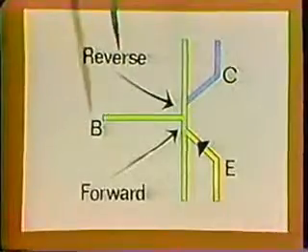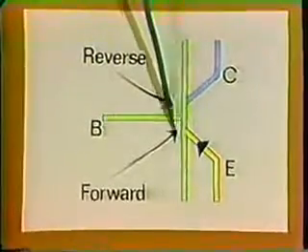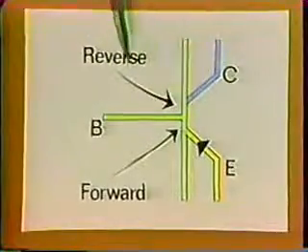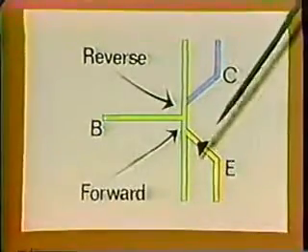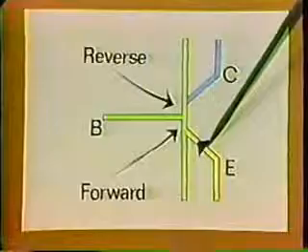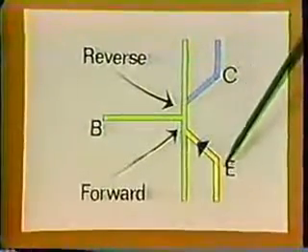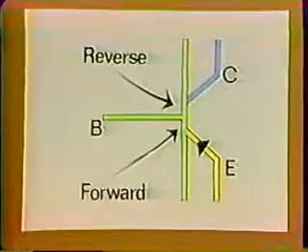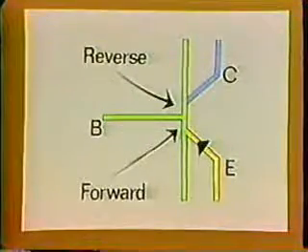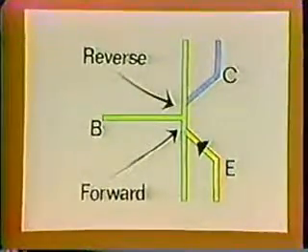In order to obtain amplification through a transistor, the base emitter junction must be forward biased, and the collector emitter junction reverse biased. It doesn't make any difference which side it's on or which direction it's pointing. The leg with the arrow is always the emitter.